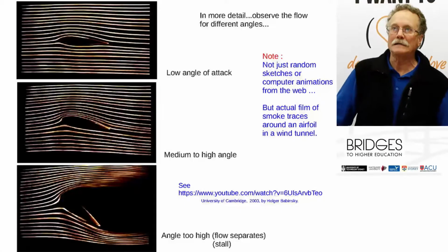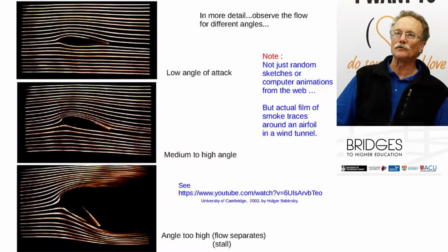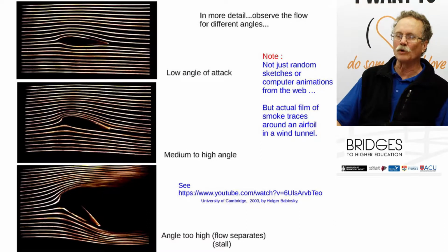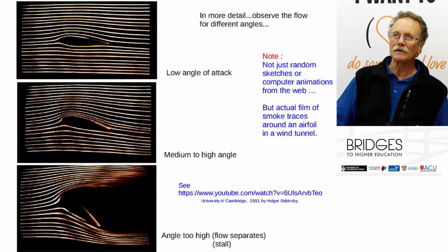So we've got a wing inside of an actual wind tunnel flow. We'll introduce smoke lines, and we can identify what's going on by looking at the visualization. Particularly, have a look at this middle picture. You'll see at an angle of attack, so we put the wing at incidence, the flow is actually changed. It's not just deflected, it's modified upstream around the aerofoil and then modified downstream. Now, from small angles to large angles, there's a modification to flow, hence we get that linear result, more lift coefficient for higher angles.